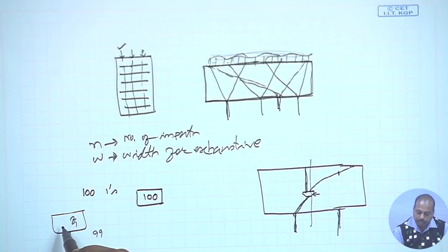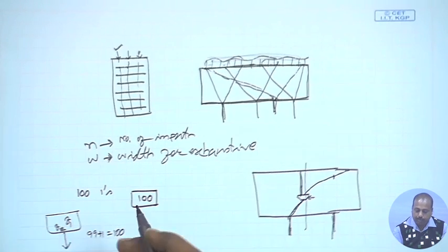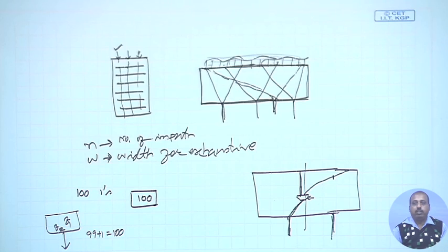But due to the presence of another fault F2, the ones count increases, so that makes it 100. So, at some point, for some input pattern where the output should not have been 1, it has become 1, as a result the ones count has increased, and for some other pattern where the output should have been 1, but it has become 0.